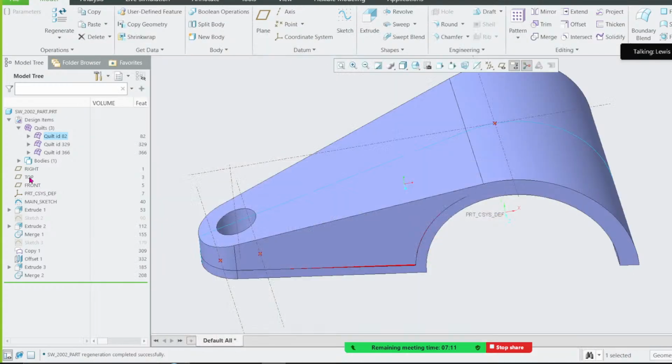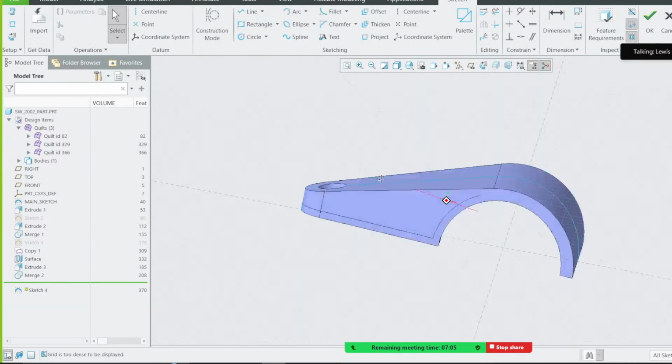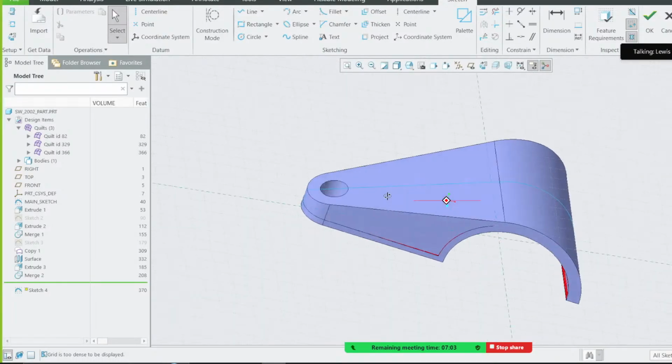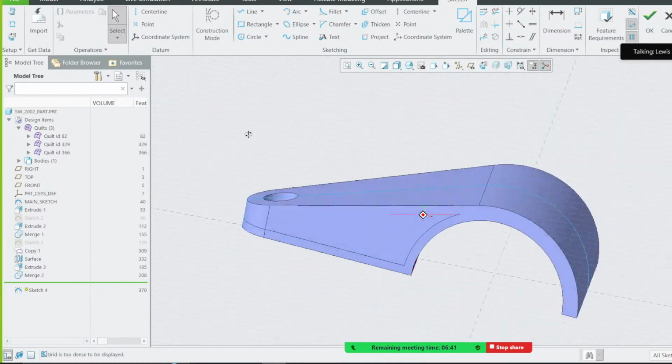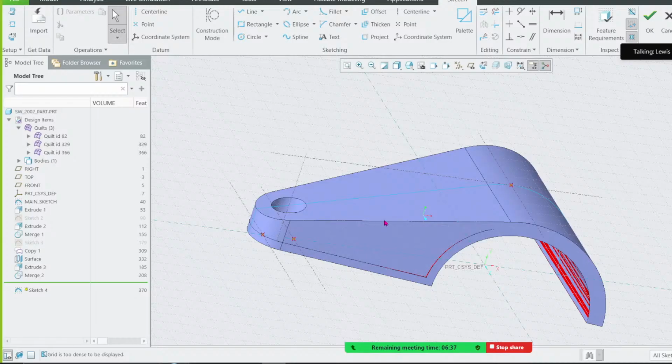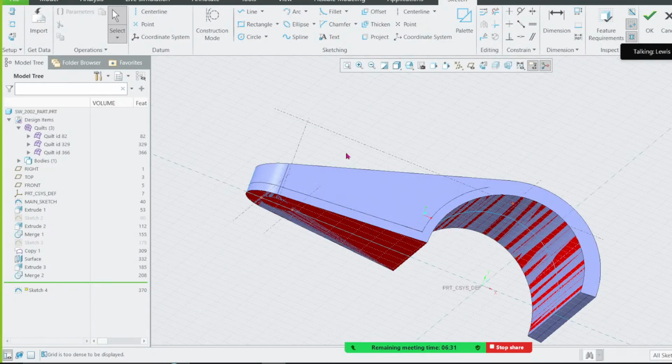I'll go back to the top view like that and avoid referencing a child. Always go to the foundation. If you're building a house, you always reference the ground. Therefore, in the case you want to design something, don't reference the top edge. Reference the ground edge because this can change. Someone can put a round, a fillet, but the ground one will never change. Therefore, I'm going to reference the ground.